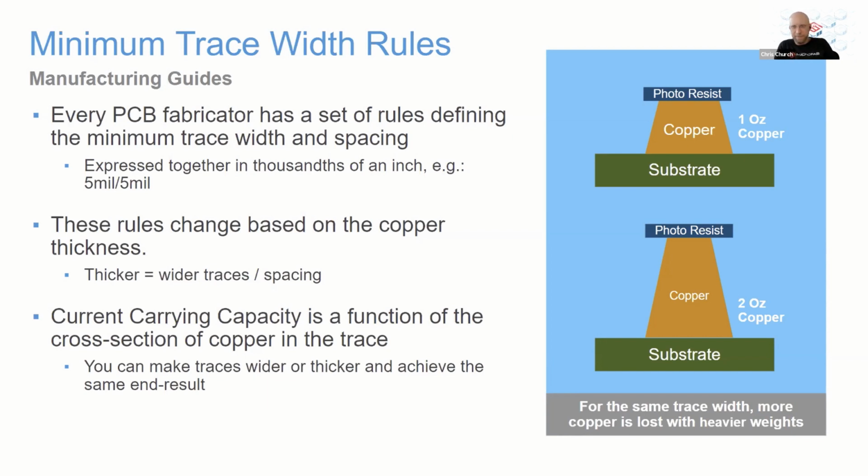So you can stack up different copper weights in different layers, but one layer can only be one weight. So, Chris, just to be sure, I'm not able to use 2 ounce copper or larger. It's not preferred on the inner layers, it's preferred on the outer layers. It is possible to do it in the inner layers.